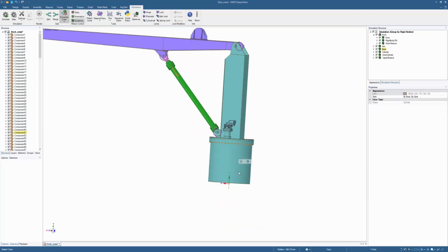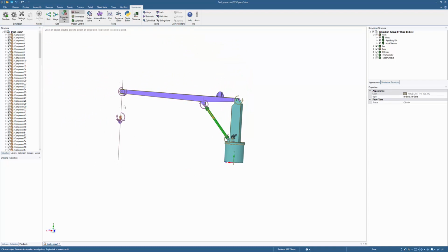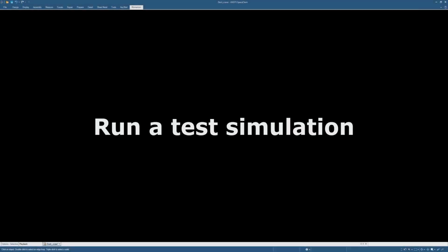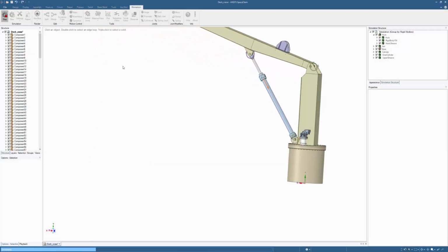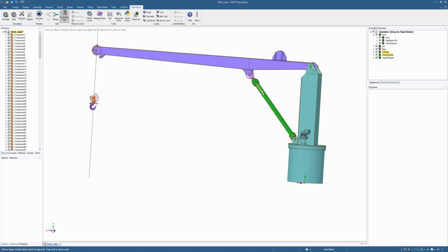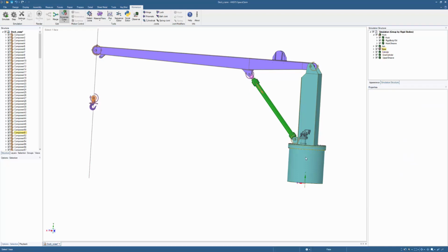And if we make the base static, meaning that it doesn't fall in gravity, we can start the simulation and see what happens. What we'll notice is that the hook construction will just fall in gravity, because right now there is nothing holding it up. So if we start the simulation, we'll see what happens. We can see that the crane arm is moving up because the prismatic motor is expanding with 100 millimeters per second, exactly like we wanted. But we set the speed to 0 before we continue. Also, we set the base back to dynamic, because we want that inside of our Unity simulation.